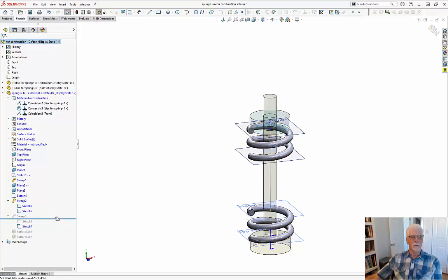Now for this third one, I'm rolling it back funny so you can see the order it was created in. I created a third straight line which just connects one straight line with the other one. Those 2 sketches at the top and the bottom that we used for the paths of the 2 sweeps, I added one more line between them.